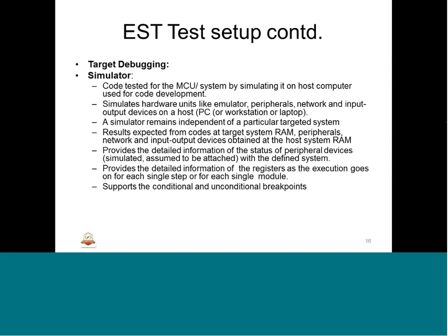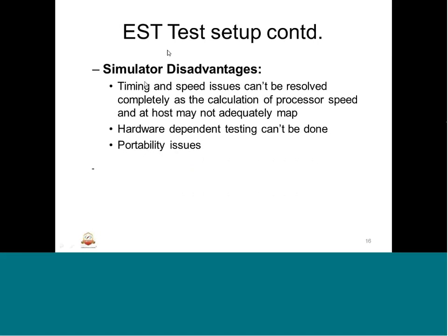But a simulator will have some disadvantages. Timing and speed issues can't be resolved. As I said, the actual timing of the microcontroller or the processor with the actual load of the signals or with the actual peripherals or devices connected will definitely vary from whatever we use in simulation. So those issues we may not be able to test completely, because the processor speed and the host will not be adequately mapped. We may map one piece or one processor or one peripheral, but all cannot be synced easily with the help of a simulator.